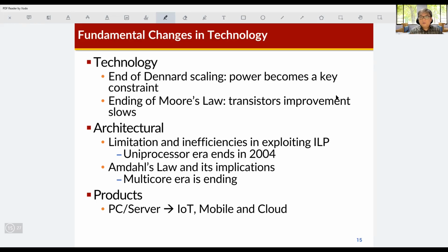Okay, but as this channel length shrinks, we can increase the system frequency of the system clock. So that will increase the power consumption. But also the power consumption can be reduced, because we can use a lower supply voltage when the channel length is reduced.